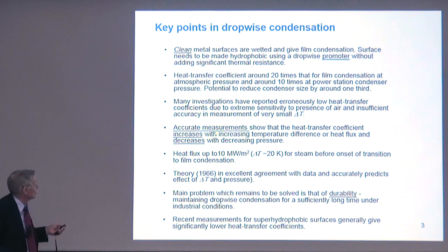Accurate measurements. Many investigators have reported erroneously low heat transfer coefficients due to the extreme sensitivity to the presence of air and insufficient accuracy in the measurement of the very small temperature difference between the vapor and the condensing surface. Accurate measurements show that the heat transfer coefficient increases as the temperature difference increases, which is rather unusual.